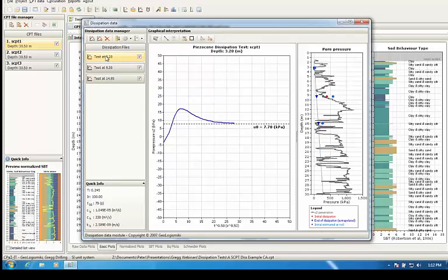Next question: what is the best way to check ch estimated from CPTu? He was comparing it to a lab value of cv multiplied by the ratio of ch to cv obtained from literature, but gets lots of deviation. Yes, I mean, that's just as I said. How do you check it?